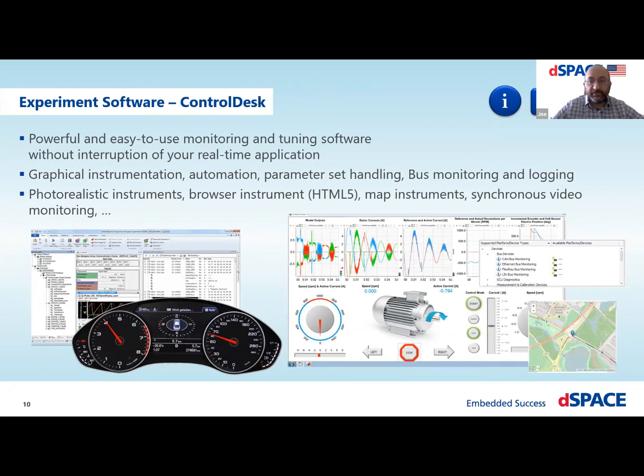Basically, what you do is you import a variable description, which is automatically generated for you from the build environment. That lets you map out the variables that you want to trace, plot, and also to tune. So data acquisition, as well as parameter tuning or calibration, as we call it, to be able to calibrate the gains and constants in your model to get the desired performance throughout your testing.